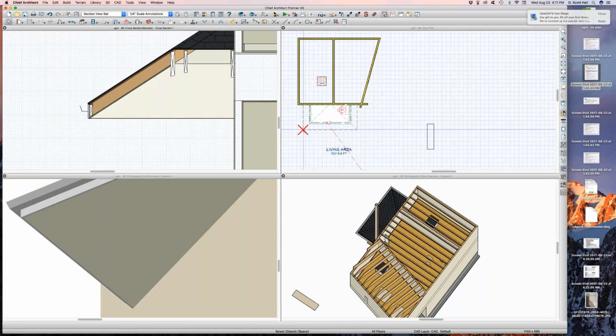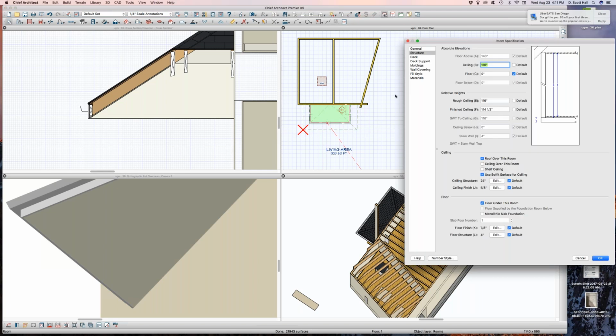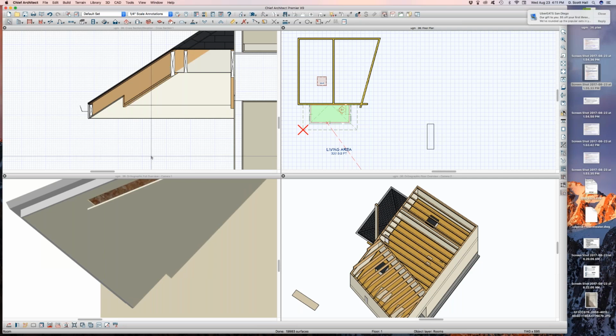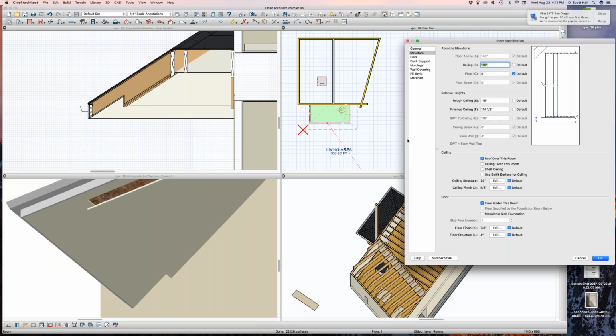Got it. Wow. So if you have that material preset for your soffit, then when you're doing the porch, just let it populate the porch. You don't have to mess around. Yeah, that just cleaned this thing up. What it's doing is forcing the rafters inside the room to be the same size as the rafter tails outside, which are determined by the fascia height.